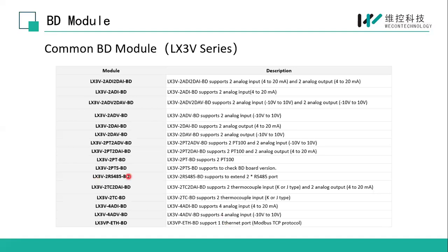Here are two communication BD boards, LX3V RS485 BD and LX3V ETH BD. These two communication BD modules cannot be used with LX5V. Besides these two, other BD modules can be used with LX5V.